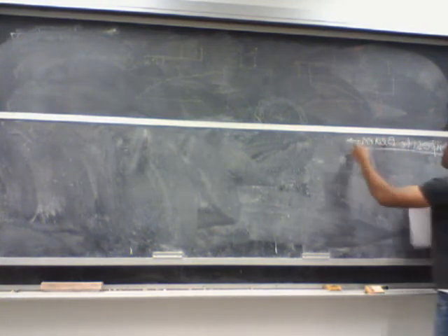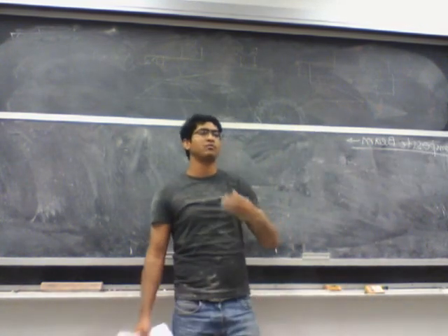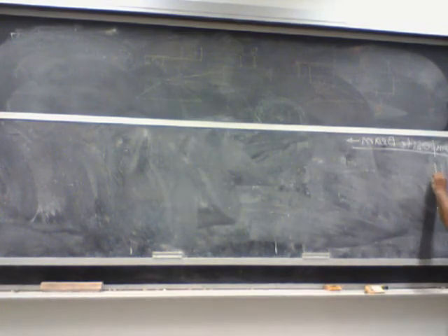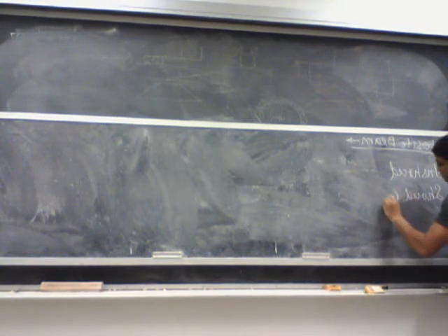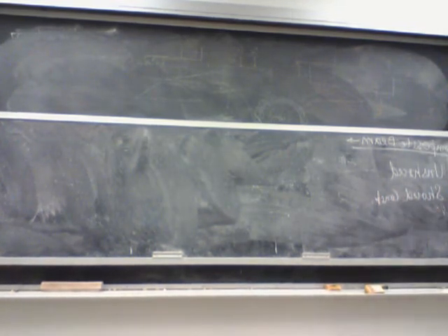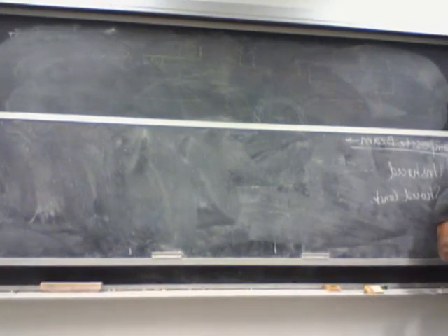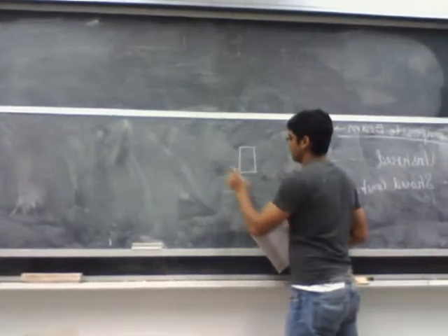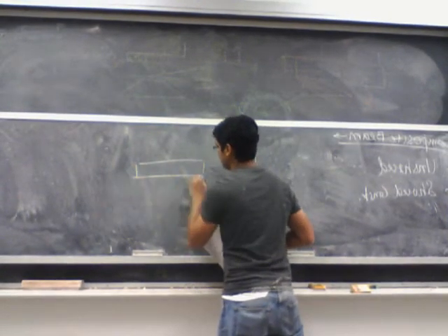In case of a composite beam, it becomes important to look at how the composite beam is actually constructed. There are two ways. The first one is unshored construction. The other one is shored construction. The difference between these two is, what you already have is your girder, which is already cast at the casting yard. So this is the cross section, let's say, and this is the beam.